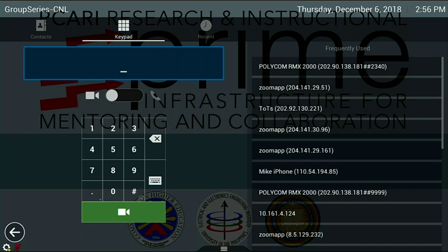That means I would have 20 degrees phase margin if it went through crossover. It's not near crossover. Let's go up here. 175 degrees. I would only have 5 degrees phase margin if it went through. I still have a huge gain. And look, it just goes straight through. That's positive feedback, and it keeps phase shifting. This thing would not meet the Bode condition.